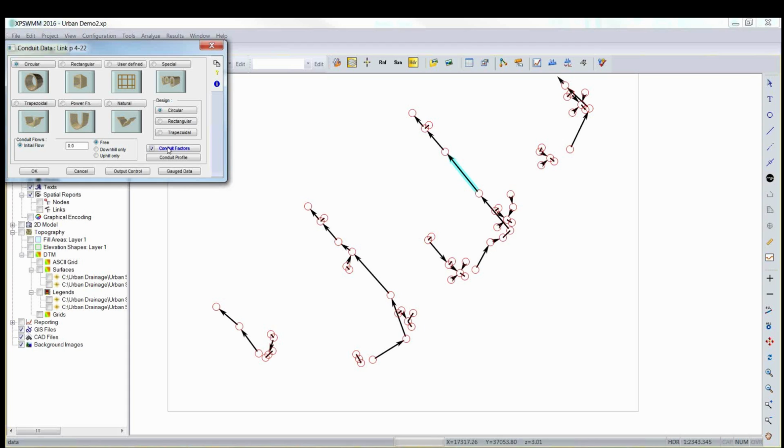Another one that we've had a lot of questions on in the lead up to this webinar is to do with pipe losses or pit losses. And so pit losses inside our software are actually not directly allocated to the pit itself. The main reason for that is because we can have very complex arrangements from any individual node or the representation of a pit per se. And so those losses are applied to the links that depart or enter into the pit, not explicitly on the pit itself.